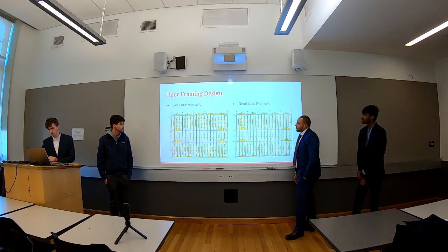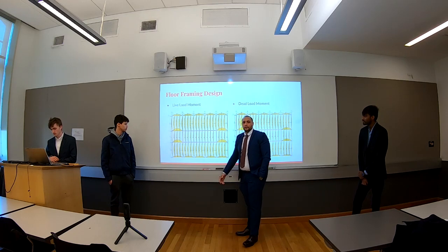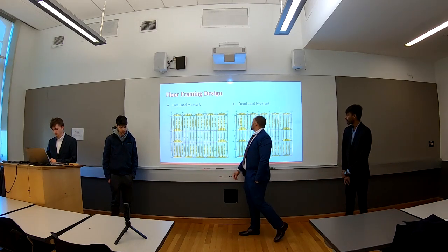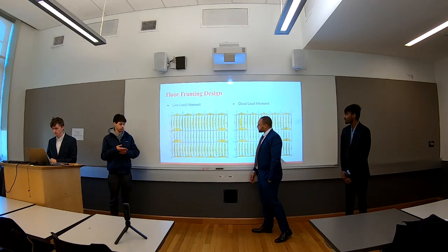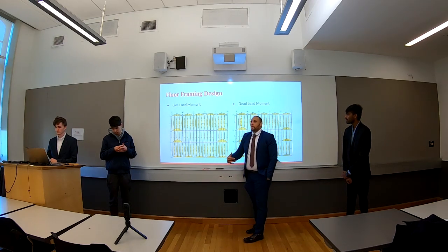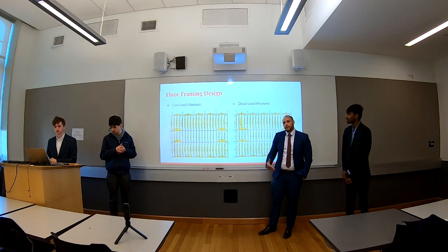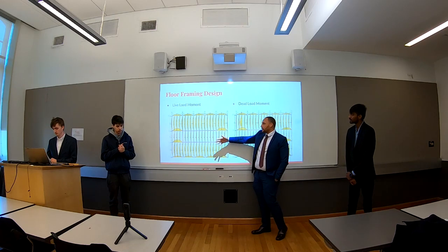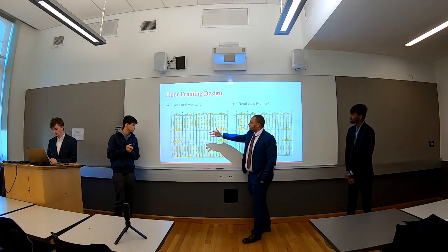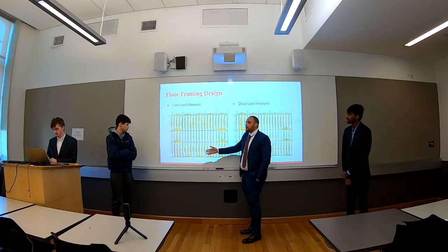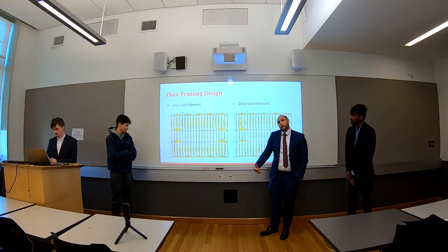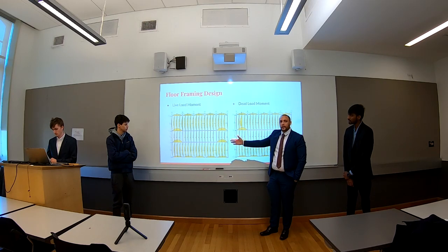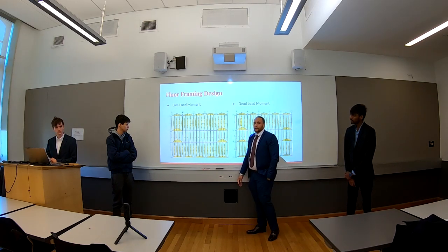So here, using ETABS, we're able to find the moment using the live load and the dead load. ETABS is a computer, so it's a tool. Even though we were able to put in our inputs with the 70 live load, and it was able to give us the moment, we also had to do hand calculations to confirm that this is the moment that is going to be assigned to the beams.